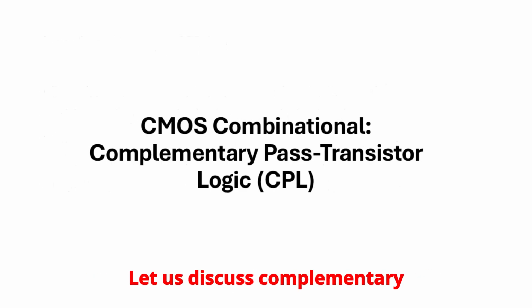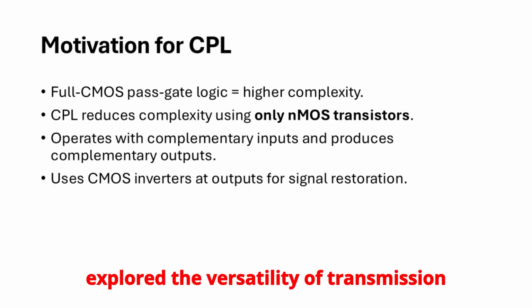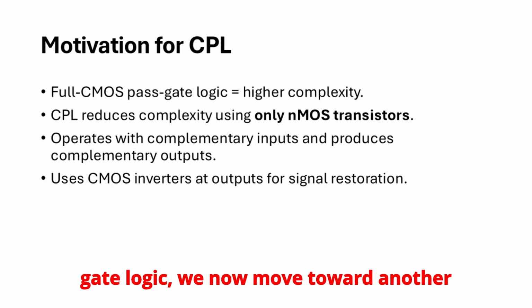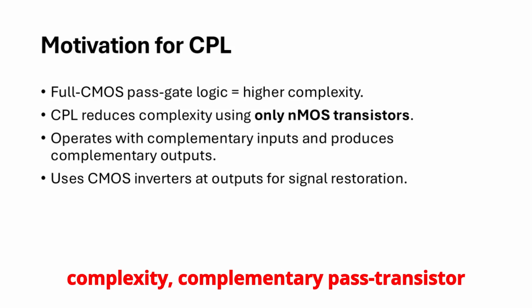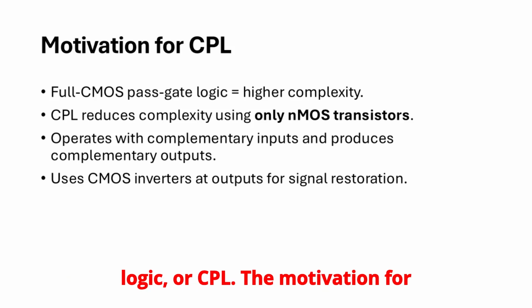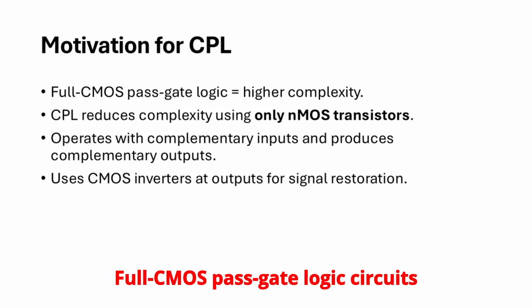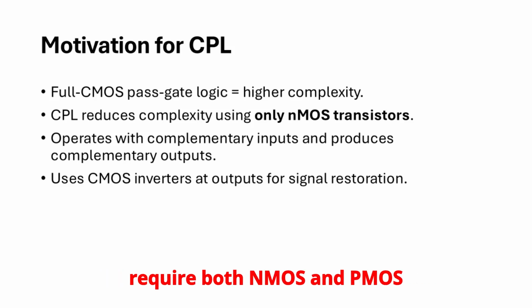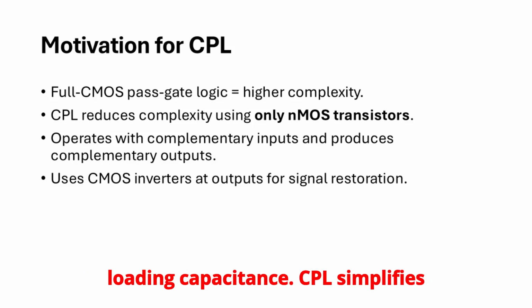Let us discuss complementary pass-transistor logic, or CPL. Having explored the versatility of transmission gate logic, we now move toward another design style that aims at reducing complexity: complementary pass-transistor logic, or CPL. The motivation for CPL comes from the observation that full CMOS pass-gate logic circuits require both NMOS and PMOS devices, which increases complexity and loading capacitance.